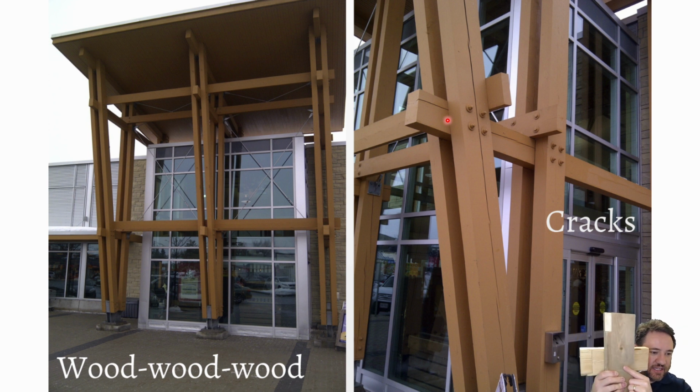In the same sense, if I had 2 bolts in this direction, then this member will not allow shrinkage, but the back member will want to shrink, so the back member would also crack. So you can imagine if I have a matrix of 4 holes here with 4 bolts, 1, 2, 3, 4, then I'll get a crack in the front member in this direction, and I'll get a crack in the back member in this direction, which is exactly what we see here.